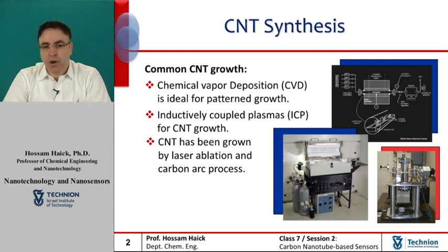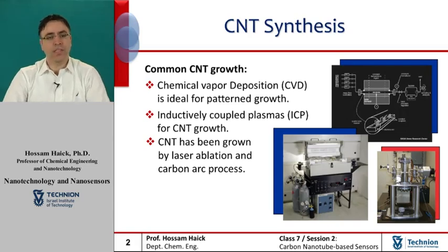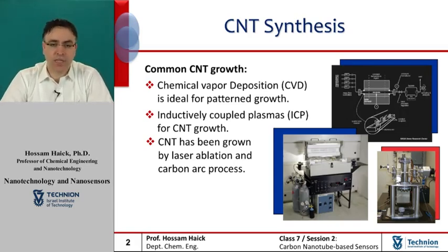Gas phase methods are volumetric, and hence they are suitable for applications such as composite materials that require large quantities of nanotubes and industrial scale synthesis methods. One of the disadvantages of gas phase synthesis method is low catalyst yield, where only a small percentage of catalysts form nanotubes.